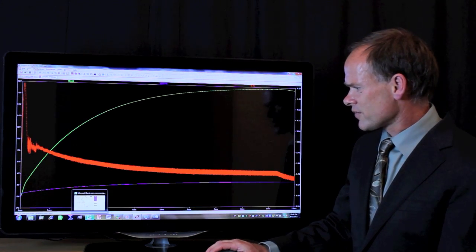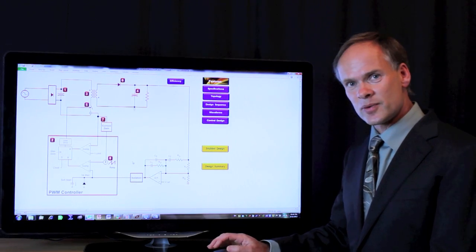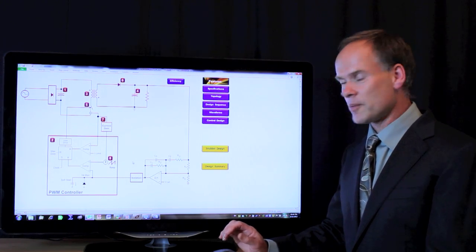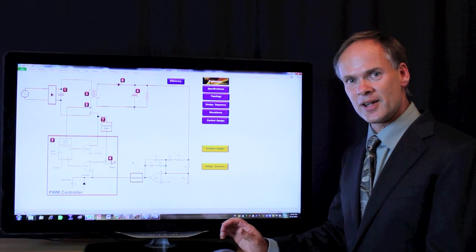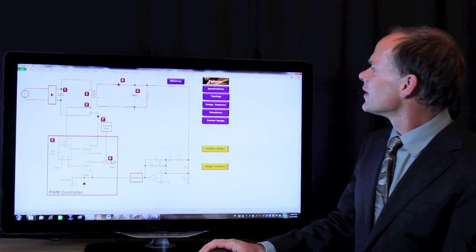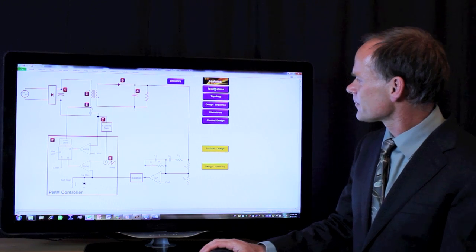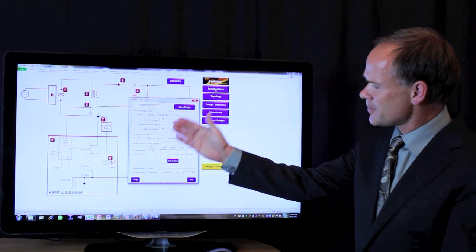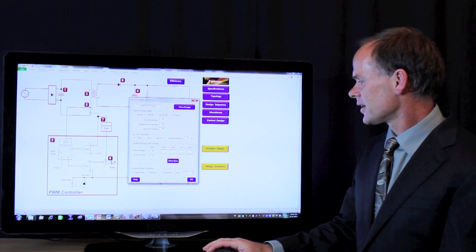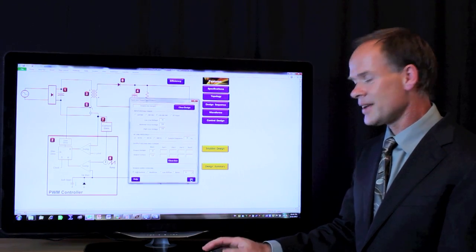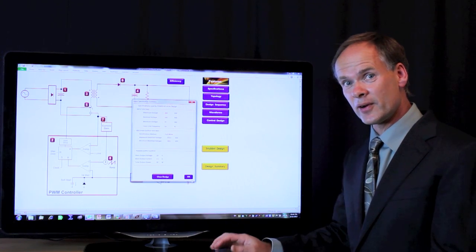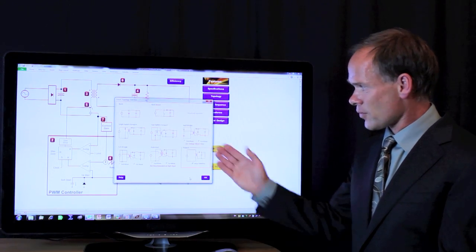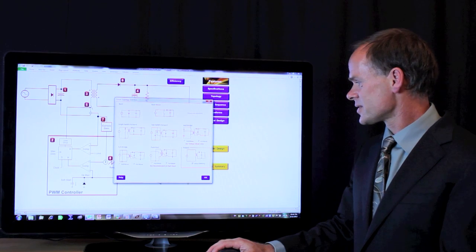So Power 456 really can help you when you're designing your switching power supply stages. Right at the beginning of the design, when you start with the spec, you put them into the program, and immediately you're getting simulated waveforms. In fact, when you run the simulation program, all you need to do is enter your input specs and your output specs for the converter. You click OK, and it immediately designs the entire converter for you. It doesn't just run a simulation, it's choosing all the parts for you for whichever one of these topologies you might want to use.